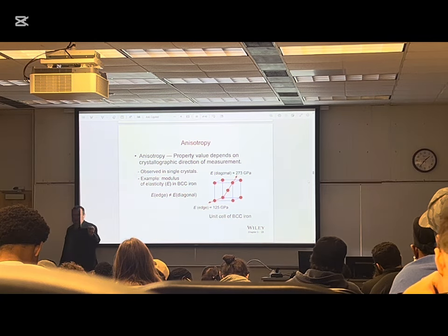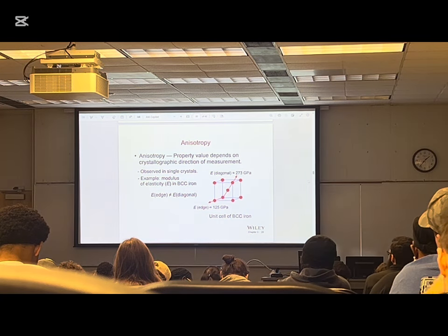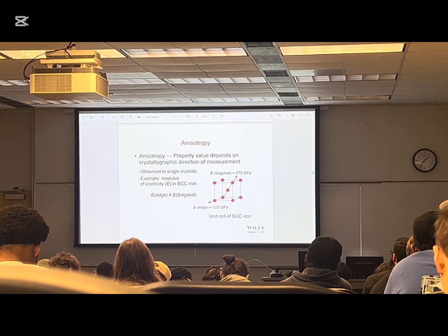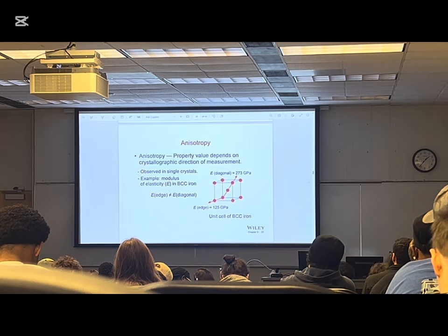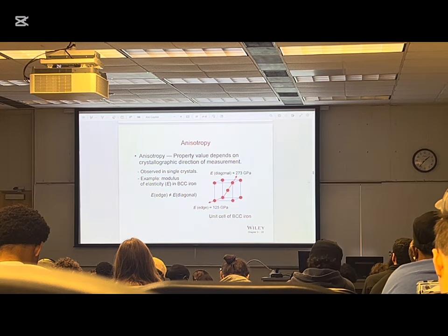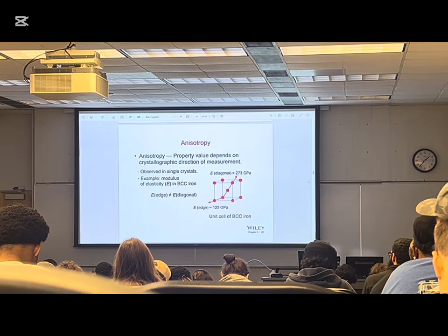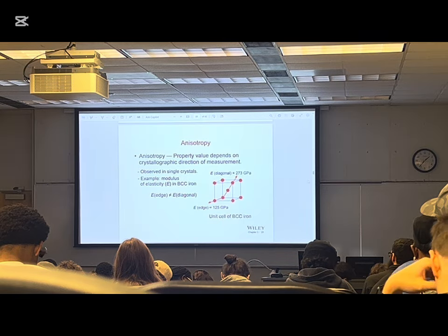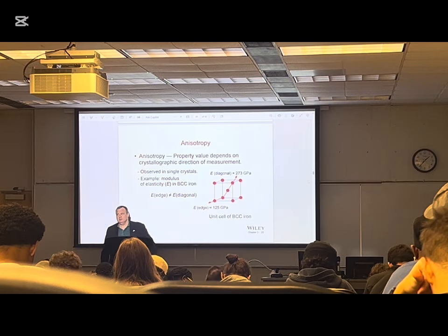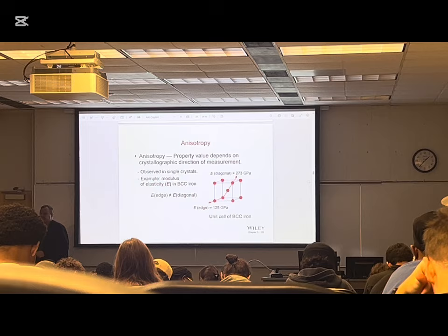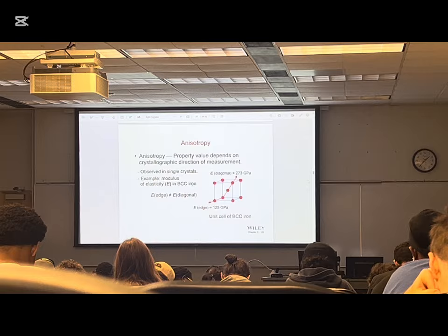So if I'm pushing this way, I'm not touching two atoms that are right next to each other. They're not nearest neighbors. So if I push this way, there's going to be a force projection that pushes this way, and then eventually pushes this way. This is why the stiffness along the edge is less than half: 125 gigapascals versus 273 gigapascals.